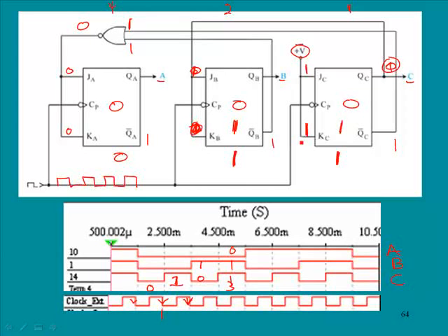Okay. Now, 0, 1, 1 is our current output. On the next clock pulse, this one is always going to change. And recall that we have a 1 going over here, so there's a 1 here. So on the next clock pulse, it will toggle from 1 to 0. And so the count that we're going to is 1, 0, 0, which is 4. But we're at 3 now, so we can see that these two will change. This one has to go to 1. Now let's look at the conditions that will make this go to 1. First of all, this is a 1, this is a 1, so that means that we have a 0 here and a 0 here. So the QB naught and the QC naught are both zeros.